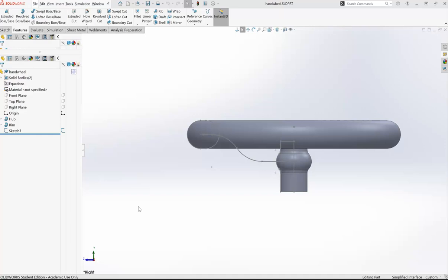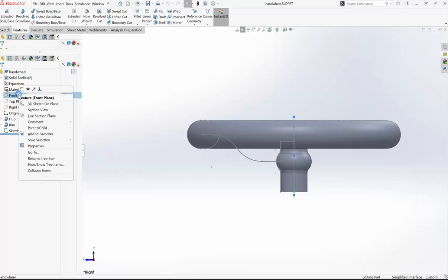With an ellipse, though, we need to define or constrain the length in at least one of the axes. A lot of times we'll use a horizontal constraint between the center and the end of the main axes, but we'll go through this in a second. So to start this, we're going to create a sketch on our front plane this time.